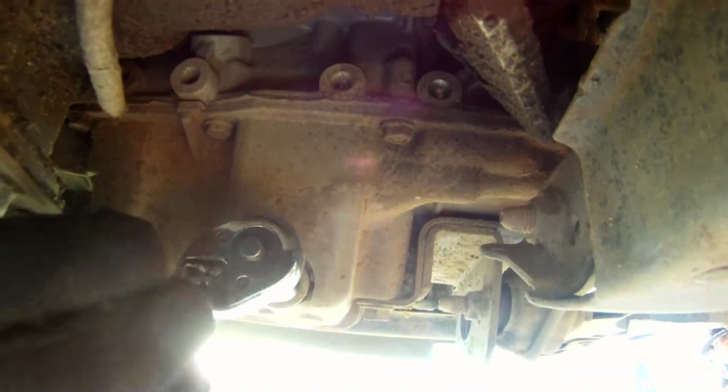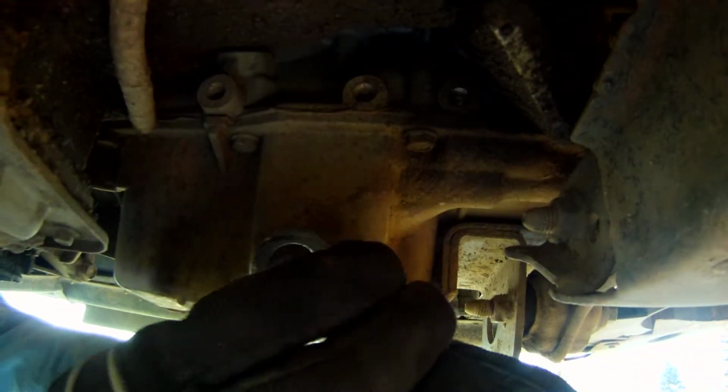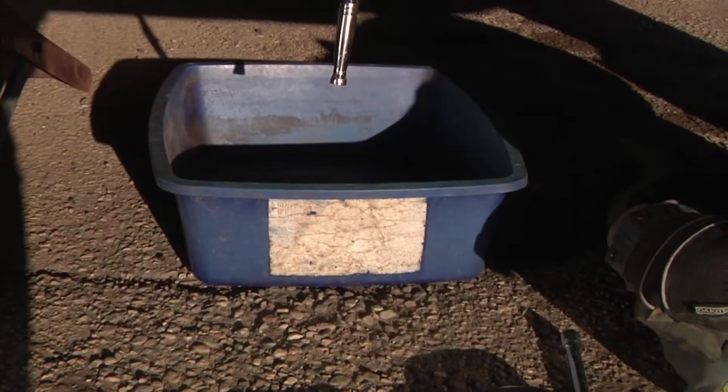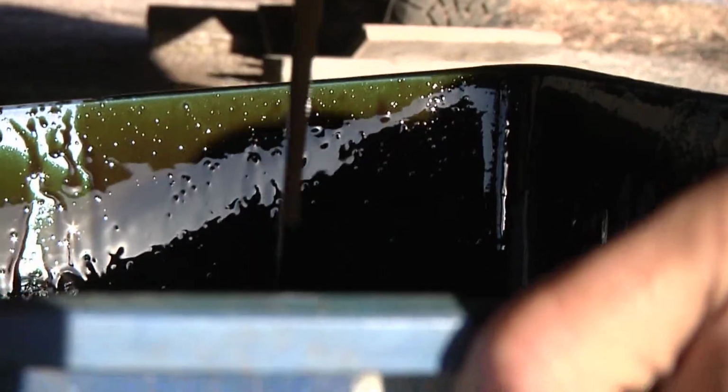Next, loosen the drain plug by turning it counterclockwise. Sometimes the drain plug requires a bit of force to loosen it. After loosening the plug, make sure the catch container is lined up underneath. Now remove the drain plug from the pan. Make sure not to drop the plug bolt into your catch container, or else you will have to fish it out of the waste oil. Be careful of potential oil splatter on yourself, as the oil will be very warm.